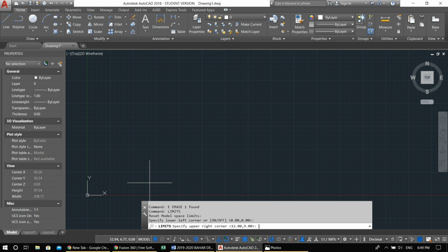For example, if you check the drawing that I gave you, you can find the link down below. It should be a little bit larger than your drawing. So I'm putting 3000 by 2000. Always put the X direction first in all commands that require two dimensions, X and Y. Always X first, then Y, then Z. We will get to that later. So if I want a rectangle 3000 by 2000, horizontal, like landscape, I'll put 3000, comma, 2000.